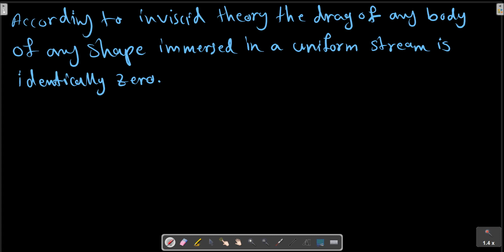D'Alembert published these results in the 18th century and pointed out himself that it did not square with the fact of real fluid flows. The unfortunate paradox caused everyone to overreact and reject inviscid theory until the 20th century, when Prandtl first pointed out the profound effect of the thin viscous boundary layer on the flow pattern in the rear, as Chapter 7 described.